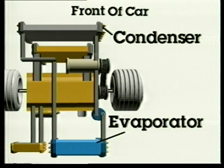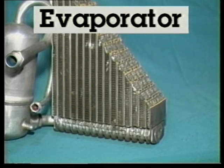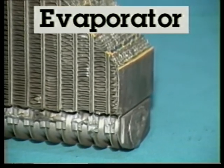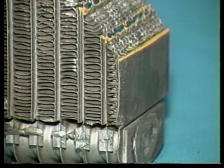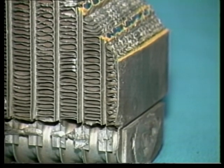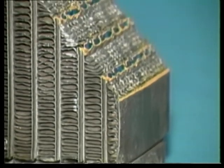Since the condenser must remove heat from the refrigerant, it is normally mounted in front of the car's radiator so that cool air can pass through the grill and condenser fins. The evaporator is mounted under the car dash so that it can absorb heat and cool the air entering the passenger compartment. We've cut this evaporator in half to show its construction.